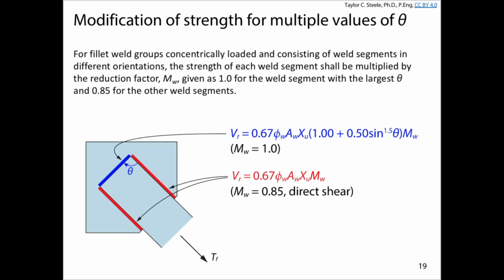So, yeah, that's the first one. Is this going to be a field welded connection or a shop welded connection? That's going to have implications on the process, maybe how many welds you specify, because there might be different positions for that welding, and the size requirements, right? You can only weld up to 6 millimeters in a single pass in certain situations. Depending on the thickness of the steel, you might need 8, and if you need 8, that has to be done in the shop. Otherwise, you need to bolt it.